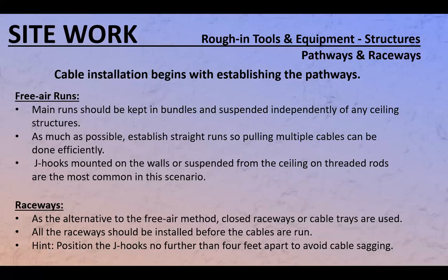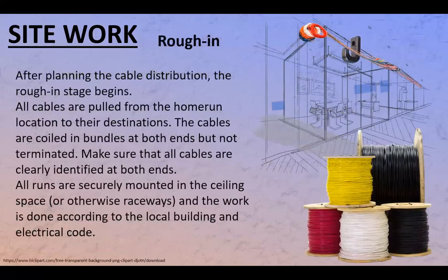And if there's so much stuff tied in and interconnected to the ceiling structure, it just makes the job that much more dangerous to the people who are responding as emergency services. So all the cabling should have independent suspension somewhere in the ceiling or some structure, so it's free, especially free from the rods that hang from the true ceiling and hold the grid for the ceiling tiles.